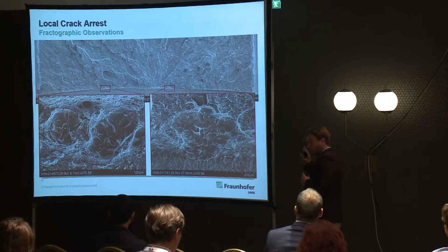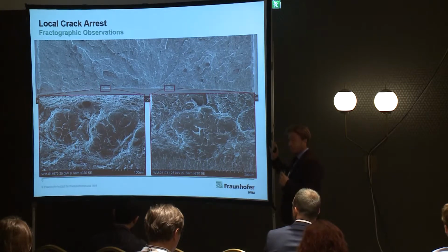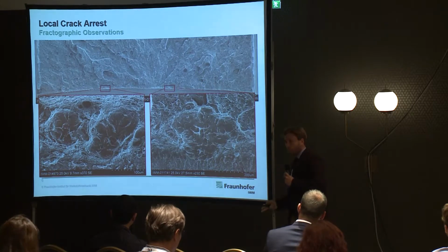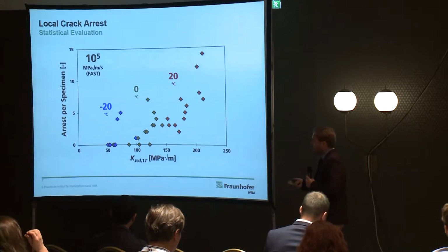But the point is here that we can imagine that this fundamentally changes the fracture behavior, because cleavage no longer is linked to the weakest link concept, where cleavage automatically leads to global failure of the entire structure, but fracture is actually postponed. Now we can quantify these arrest incidences if we count them per specimen.